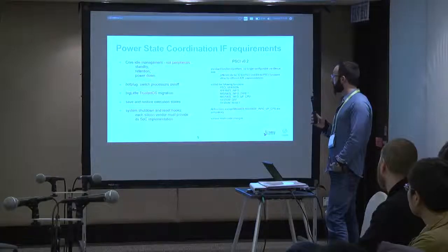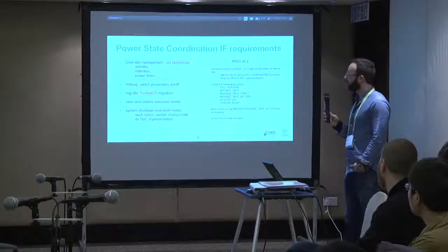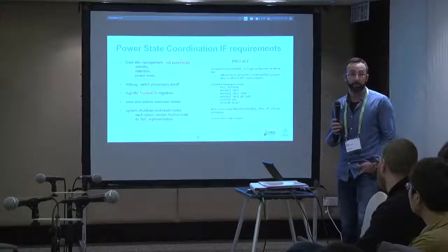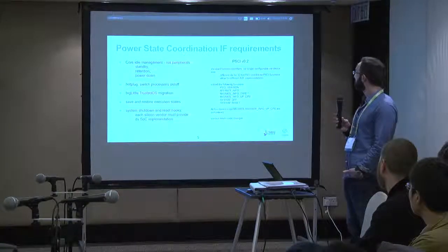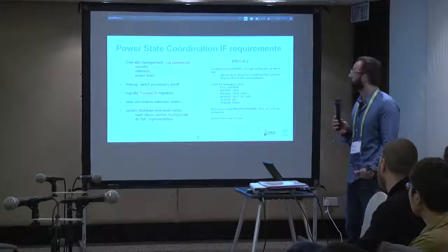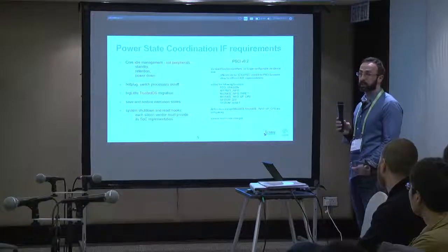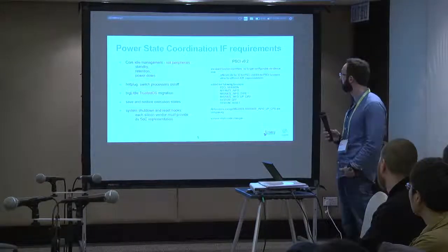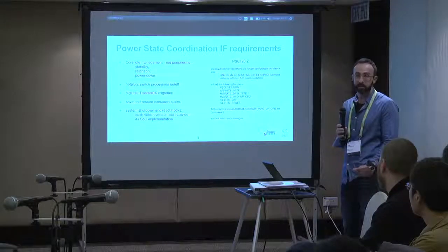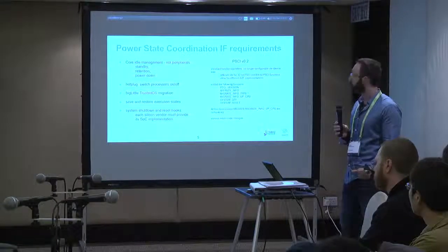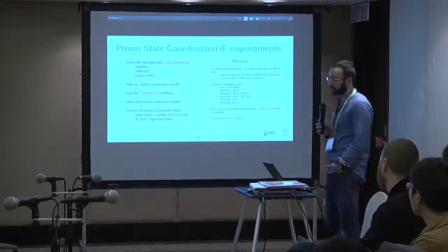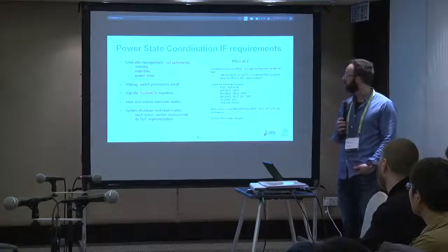The core idle management covers standby, retention, and power down. From the OS perspective, between standby and retention there are no really major differences, other than an external debugger trying to access debug registers while the core is in retention state; you won't be able to access them. Other than that, from the rich OS it's the same. Then for power down, you need to manage the context and make sure that everything is safe.